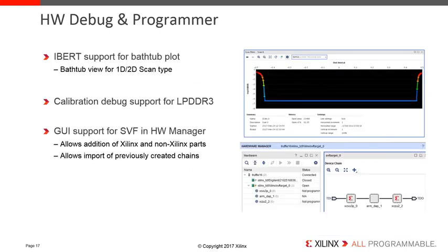Also in hardware debug, IBERT now offers support for bathtub plots, including 1D and 2D versions. Additionally, memory calibration debug support has been added for LPDDR3. Also, there is new GUI support for creating SVF chains for Xilinx and non-Xilinx parts with the ability to import previously created chains.